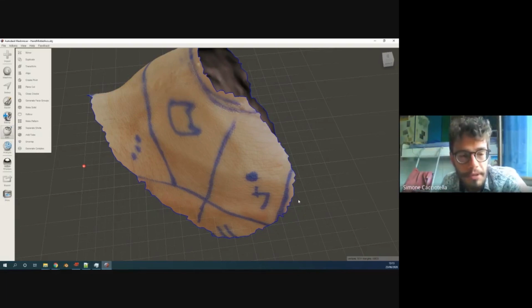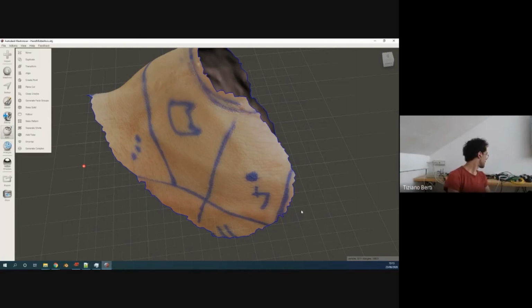How do you print these with a 3D printer? Actually, I don't have photos nor the piece right now, but it's doable with support. If you are in a medical facility with a more professional printer, you probably have an FDM machine with removable support, so you can print them in PVA and be happy with it.